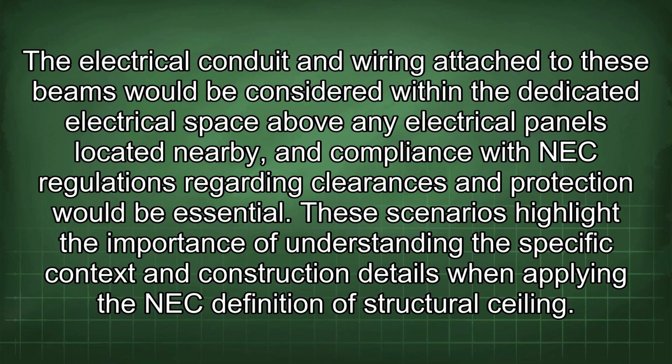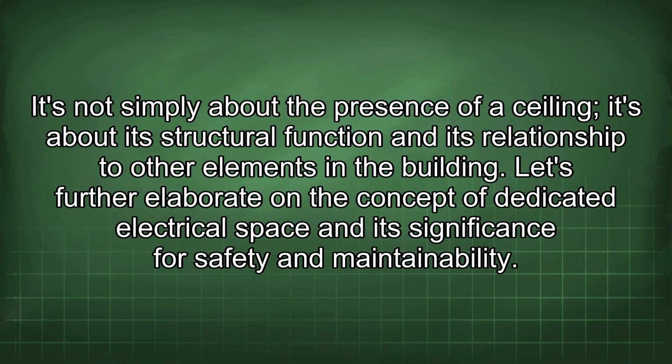These scenarios highlight the importance of understanding the specific context and construction details when applying the NEC definition of structural ceiling. It's not simply about the presence of a ceiling, it's about its structural function and its relationship to other elements in the building.